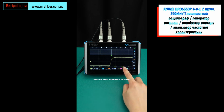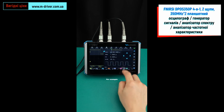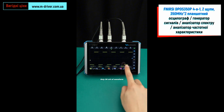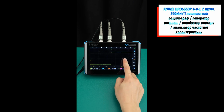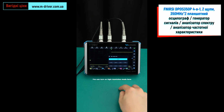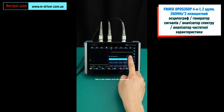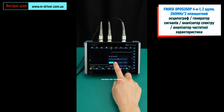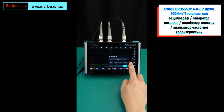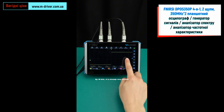When the signal amplitude is very small, for example, a waveform of only 50 millivolts, we can see that it has a lot of burrs. If you need to view this waveform accurately, you can turn on high resolution mode here. This is the effect of 8-bit resolution. It has a lot of burrs. As the resolution increases, the burrs gradually get smaller. By 16 bits, it is already very smooth.